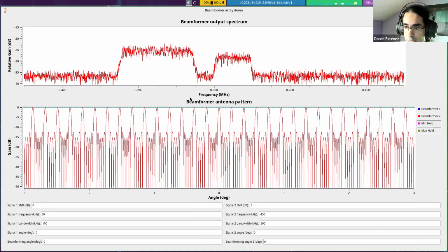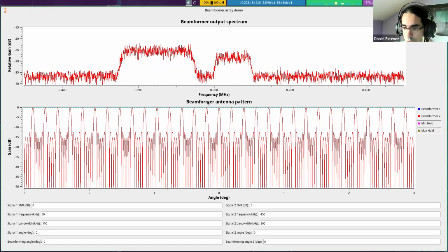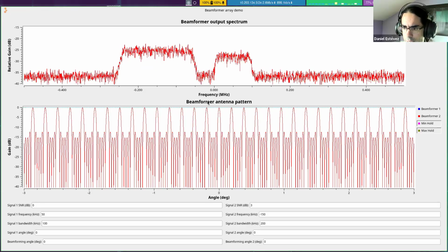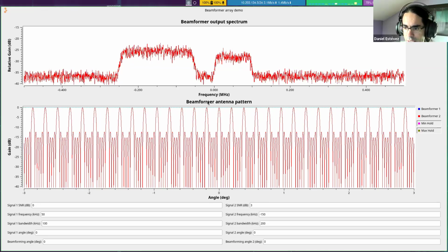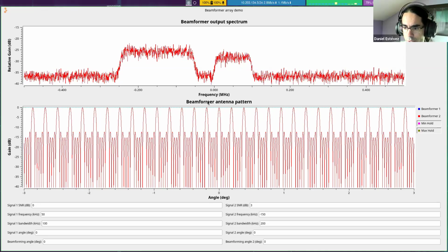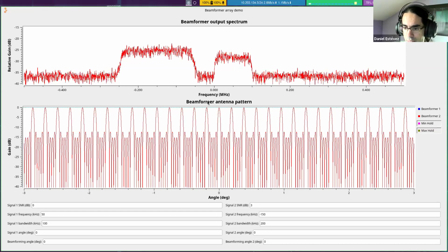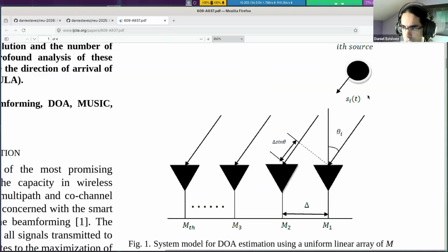The other one is I mentioned physically moving your antenna so that the grating lobes are in different places. There's a way to do that indirectly, which is that the Earth moves, or the apparent location of the source on the sky moves. What that means is that the baseline that the object is seeing keeps changing.